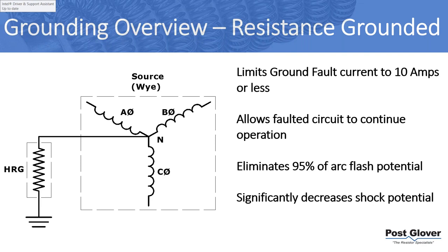And so, assuming a steady voltage, we have a scenario where we're engineering the ground fault current. I have a steady voltage, so I can make a resistor anything I want, right? You can ask for a resistor at whatever ohms you'd like, essentially. And so you can engineer your ground fault current. Therefore, you're eliminating the overvoltage, like I mentioned, and you're also eliminating the overcurrent issues that you have in a solid ground system.